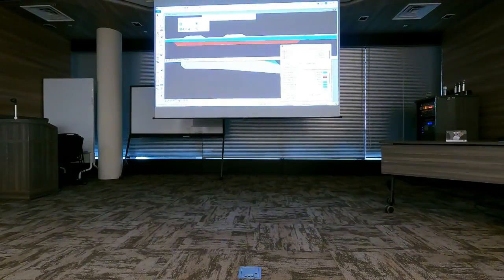But I am primarily interested in the excavation, so that's what is going to be dug out. So I can here select that the excavation is my target surface. Then when I say compute, the target surface limits where we compute volumes. By changing source to target, the volume calculation is limited to that surface model.